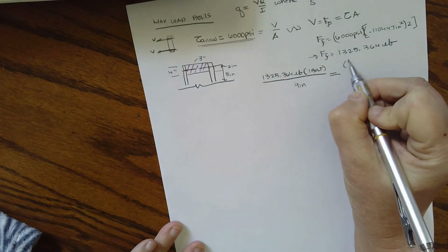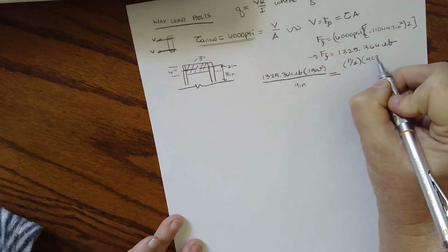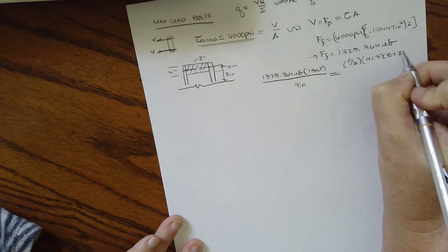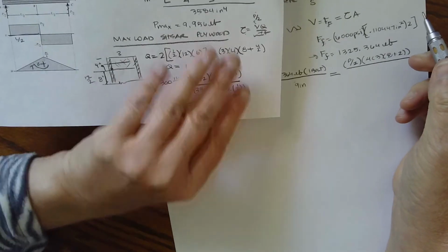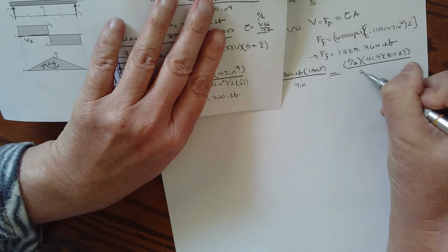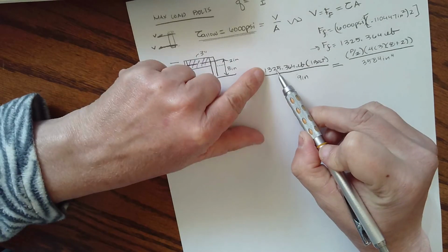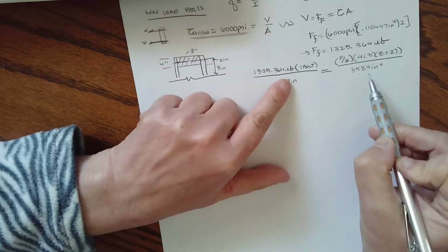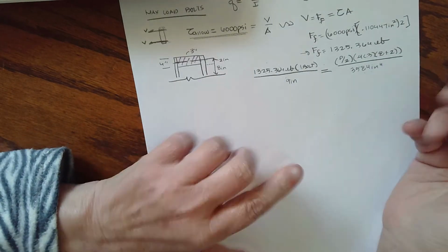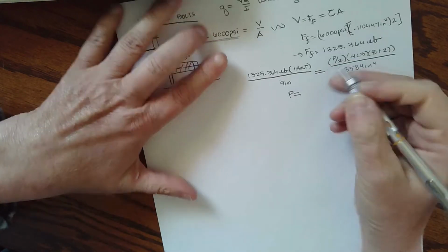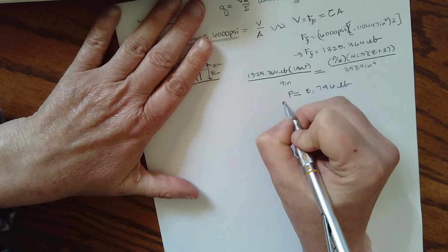So we have P divided by 2, that came off our shear diagram, Q, 4 times 3 times 8 plus 2, okay? VQ over I. I was also given as 3584 inches to the 4th. So I'm going to take 1325 times 1 divided by 9, my spacing, times 3584 times 2 divided by 12 times 10, which is 120, and I get a value of 8,796 pounds. And this is the maximum based on my bolt.